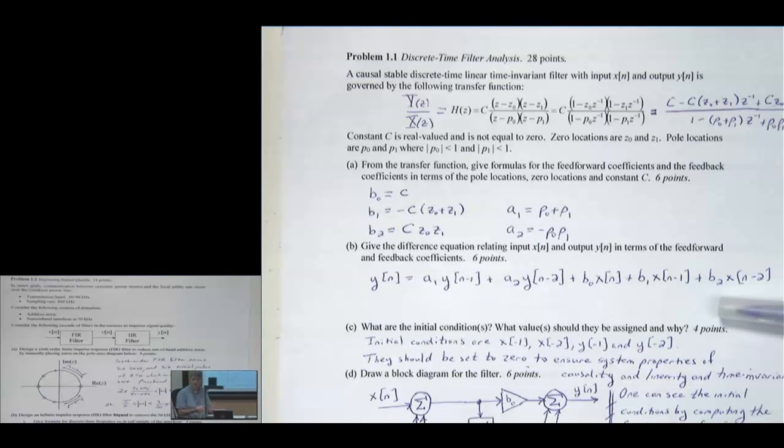So again, I don't know if that's the pressure of the test or what. First I have to find out where the passband is. We want to pass frequencies from 40 kilohertz to 90 kilohertz, and the sampling rate is 400 kilohertz. So the range of frequencies we care about is from pi over 5 radians per sample to almost pi over 2, so 9/20 pi. There are many solutions for this.